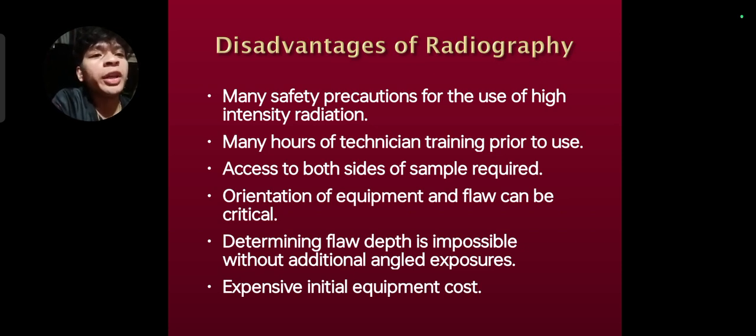Determining flaw depth is impossible without additional angled exposures. Initial equipment costs are expensive. This is not friendly, because radiography testing is quite expensive and we need a lot of money to do the testing, unlike penetrant testing, which is quite cheap, easy to use, and good for the environment as well.